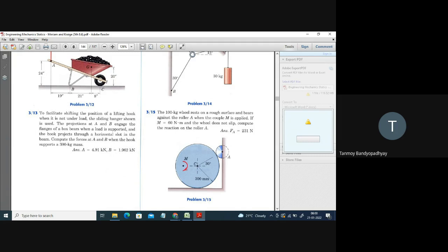Okay, so couple is a free vector. This part I had skipped a bit, we hadn't covered that chapter. So couple is actually a free vector, meaning inside this total rigid wheel, at a certain point the couple is shown. The couple is not bound to a point actually. So all the points on the entire rigid body will be subjected to the same couple.